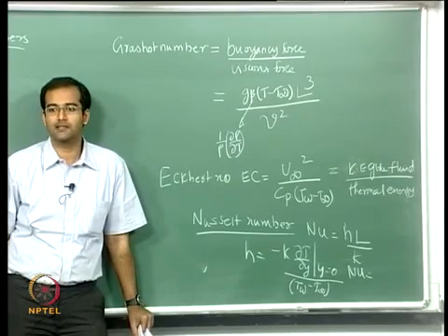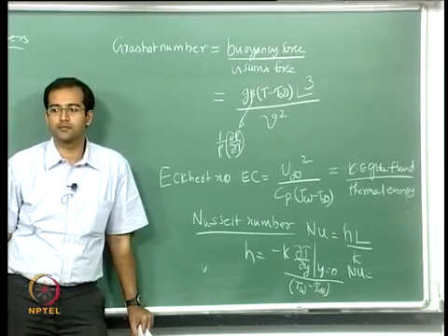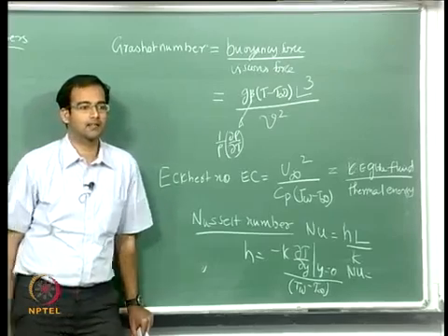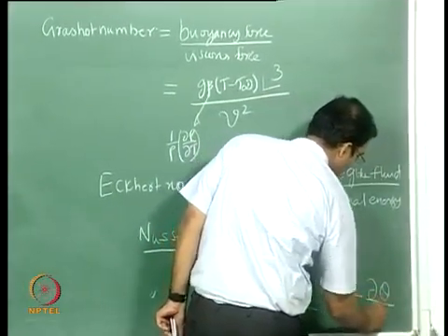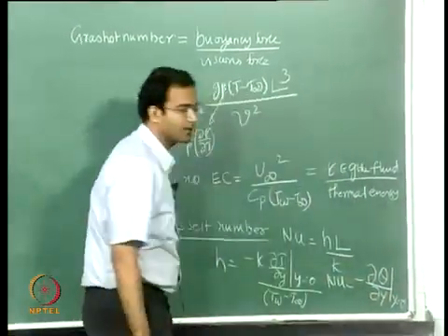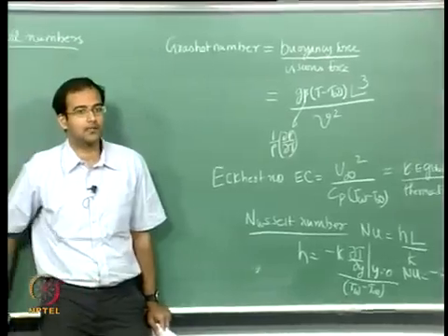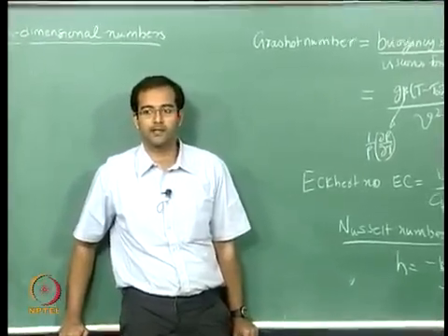Thermal conductivity cancels, and you can also write in terms of non-dimensional Y. L cancels. So that will be minus d theta by dY at capital Y equal to 0. So this is the advantage of casting in non-dimensional form. Your expression gets much simpler.